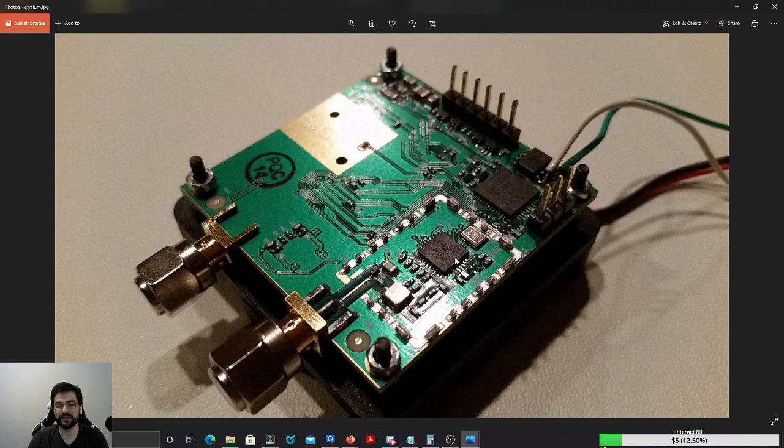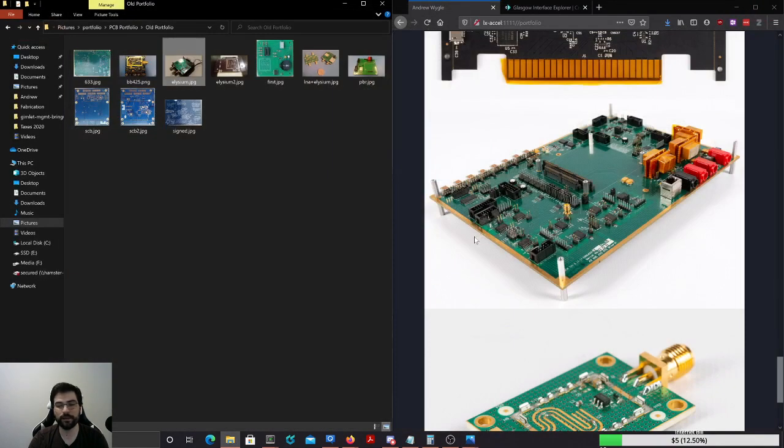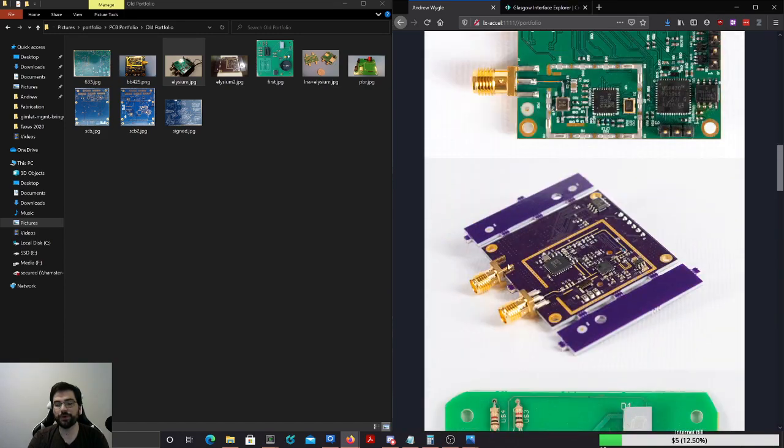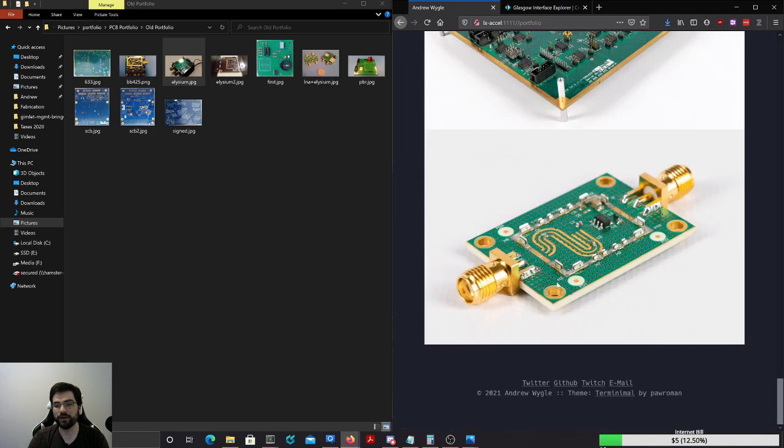Except that actually it didn't end up needing that because, I don't know if anyone but me will find this as funny as I do. But when you put holes in the board underneath a pad, the holes are called vias. When you put them underneath a pad, you want to plate over the hole so that solder doesn't get sucked down into the hole. You want the solder to connect the board to the pad. So what you do is you put an epoxy, basically a glue, into those holes before you plate the copper onto the board so that it just covers over and then you have a nice even pad.